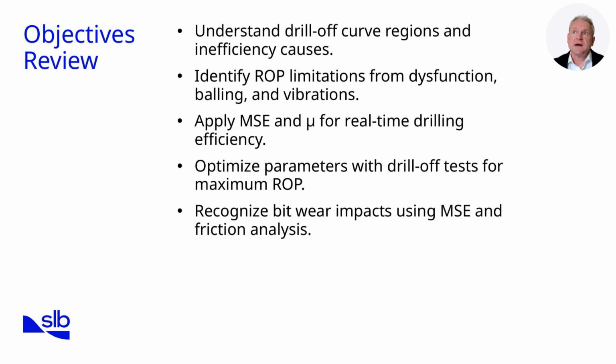Fourth, we reviewed how drill-off tests can optimize weight on bit and rotary speed to maximize penetration. Finally, we examined how MSE and MU trends reveal bit wear, helping us plan trips more effectively and avoid unnecessary downtime. Each of these objectives has been addressed through practical examples and clear diagnostic methods. This gives us a strong framework for real-time well monitoring and drilling optimization.